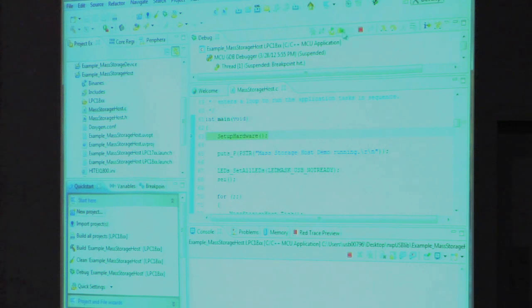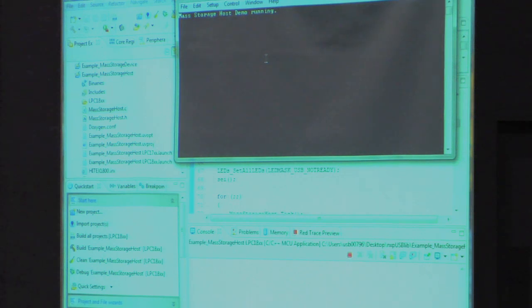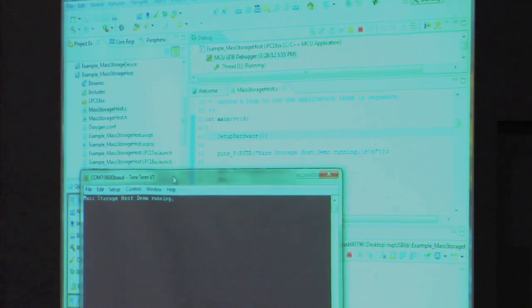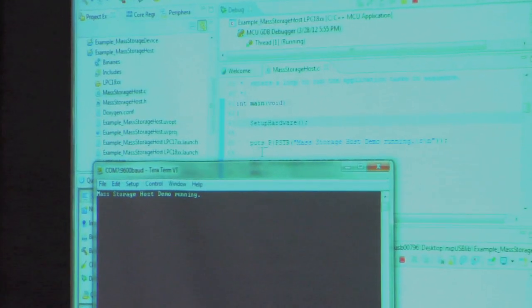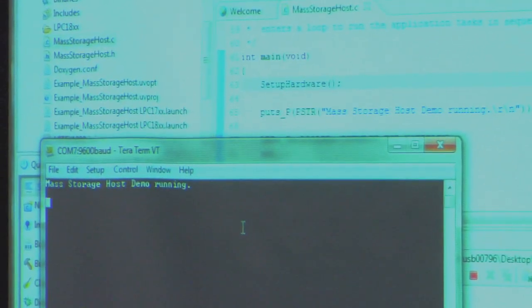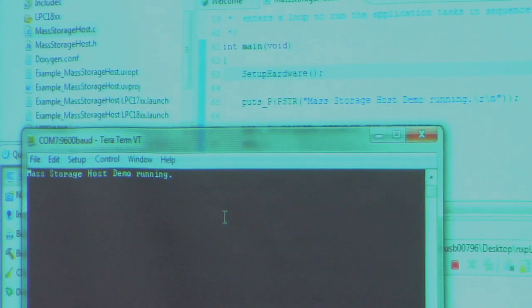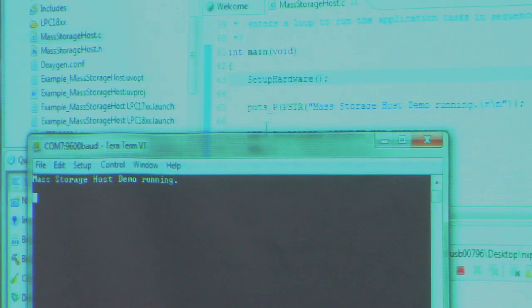So hit the play button, and I'm debugging. Now, there's the diagnostics. There's some diagnostics in all the host code, so you know that it's actually running. Here's the line of code in the example that produced this string that you're looking at right here. All right. Now, the board support package contains the code that drives the serial ports for all the different boards. So we have this one function, and it goes through the BSP, and if I selected a BSP for a different board, it would configure that differently, but you'd still get a string out on a serial port.